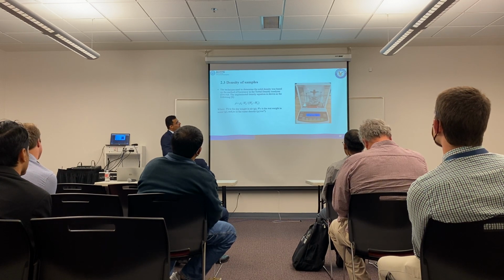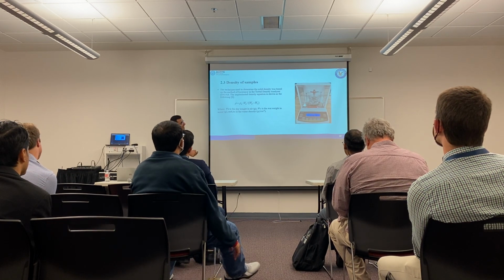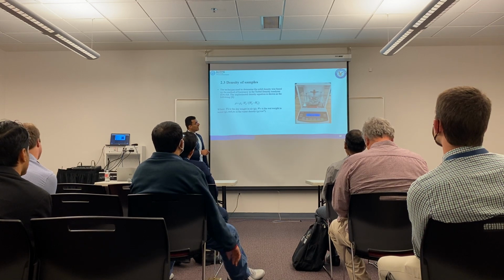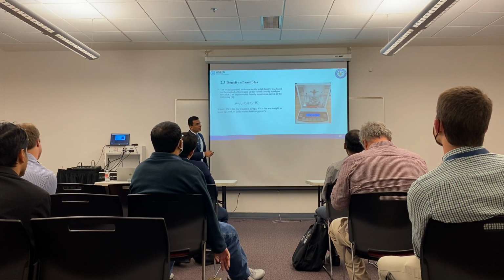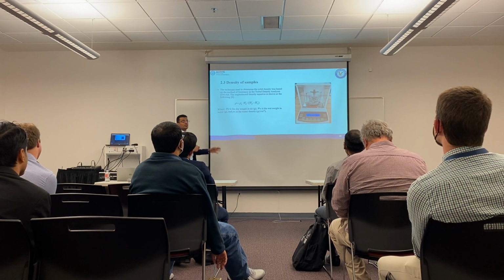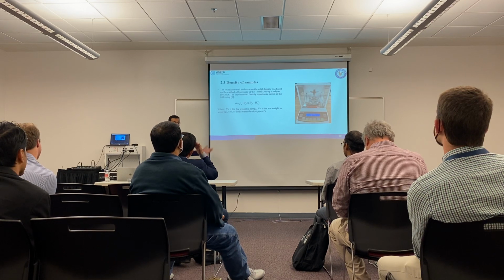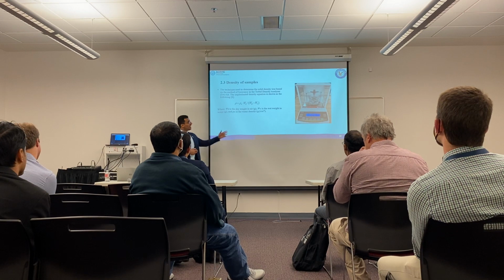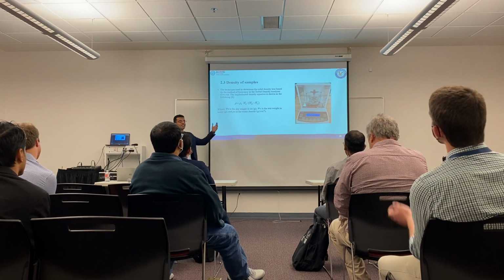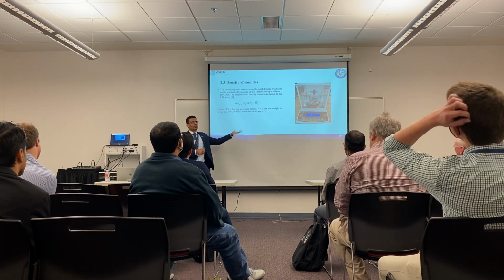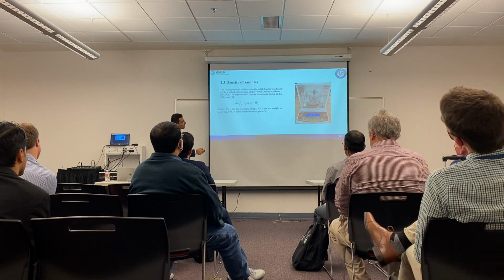We could measure the dry weight in air and the weight here in the water, based on buoyancy and also based on Archimedes principle. We will get a pure solid density for that. This device could give us the solid density and liquid density. We are just dealing with the solid density.